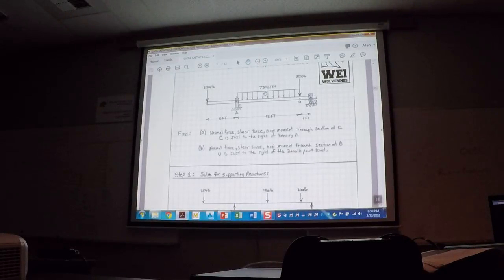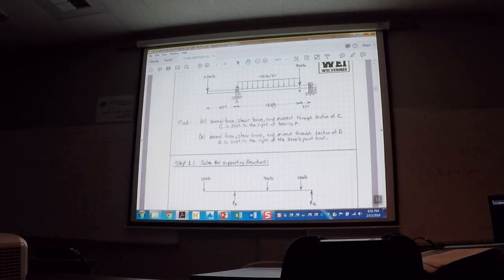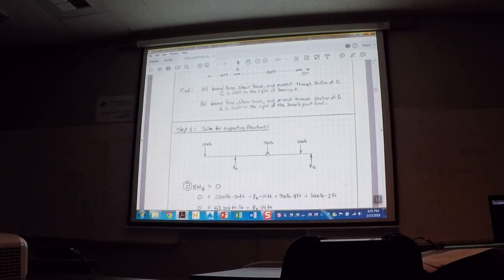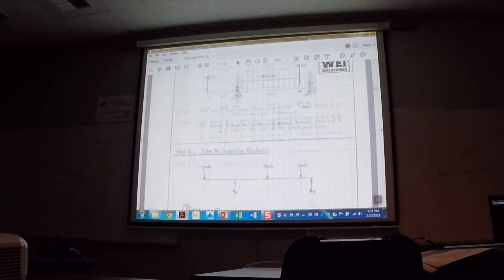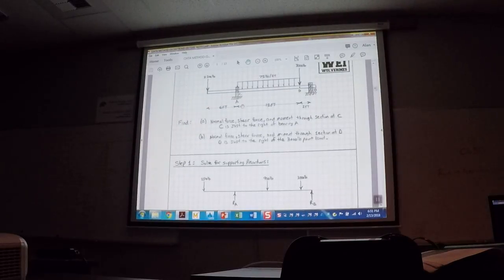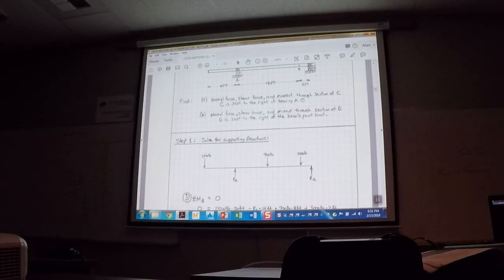As we have learned in the past, a uniform distributed load can be modeled as a single point load at the midpoint, which would simplify it, right? And if it was like a triangular load, it would be 1/3 from the base, right? And these are just point loads. So I sketched it, well, 75 times 12 is 900, and I put it right in the middle, so 12 feet, that'd be 6 feet over from that. So you're seeing, wow, 900-pound load, 6 feet over, 2,500 pounds, 6 feet over, plus 3,000 pounds, 12 feet over.